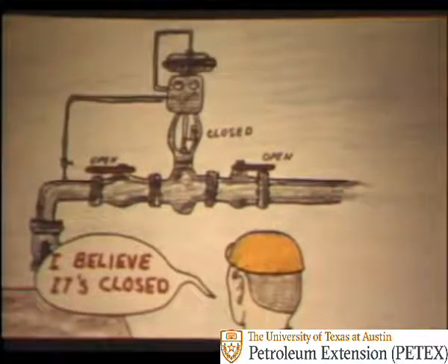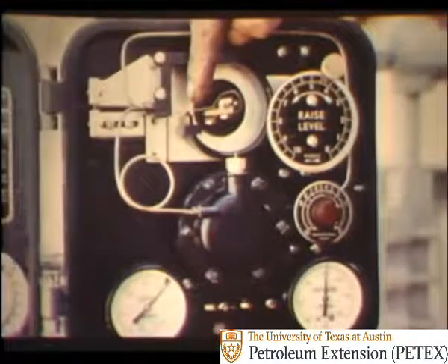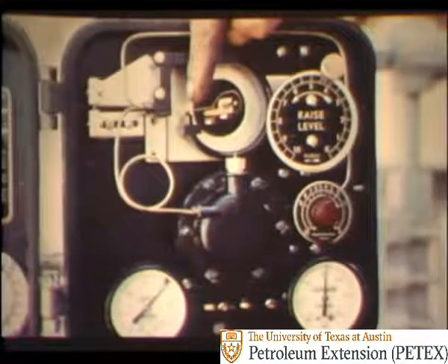First, check to make sure a block valve is not closed. Then check the gas back pressure valve to see if it might be closed. If it is, check the instrument air supply gauge on the controller. If the instrument air supply is okay, attempt to stroke the valve with the flapper. If it's sticking and won't open, block and bypass the control valve and have it repaired. If the back pressure control valve is okay, check the equipment downstream for a closed valve. Make sure everything is okay before opening any closed valve.